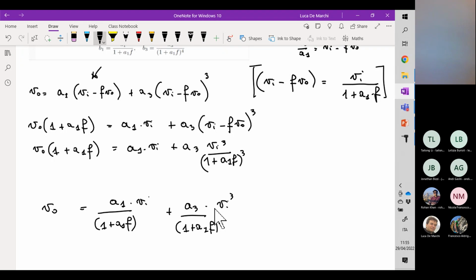In the next slide, you see the effect of the phase margin in terms of the step response. The step response has this ringing effect when we have a phase margin equal to 45 degrees, a much smoother step response when we have a phase margin equal to 60 degrees, and an even smoother step response when the phase margin is equal to 90 degrees.